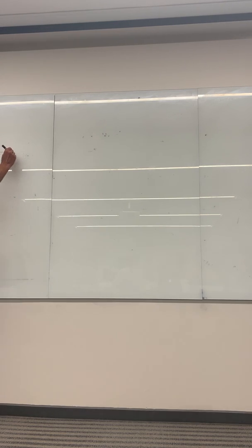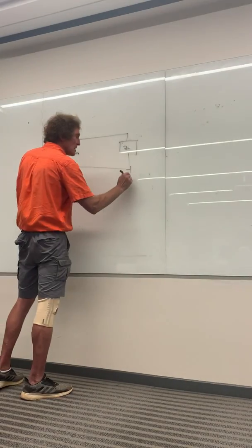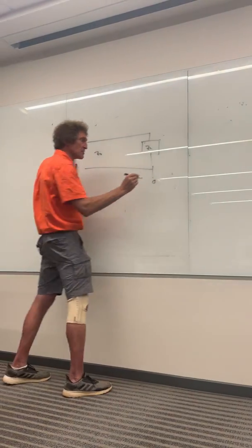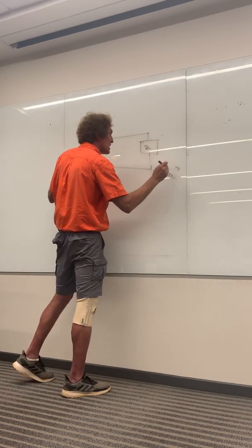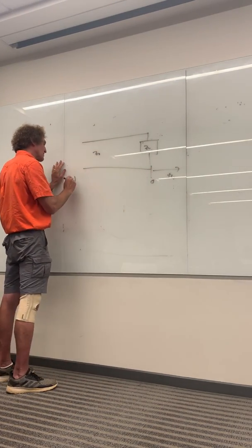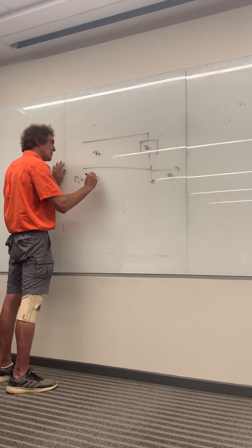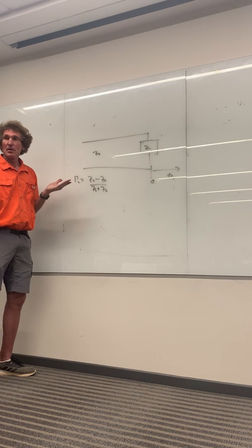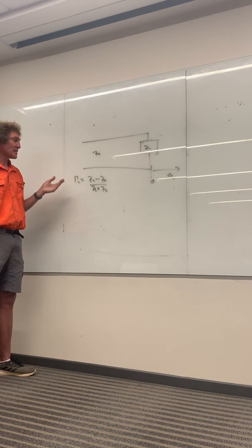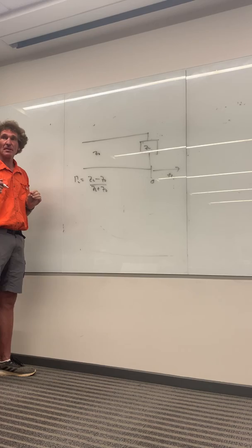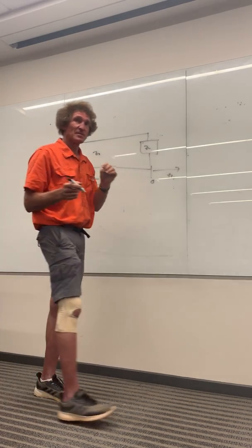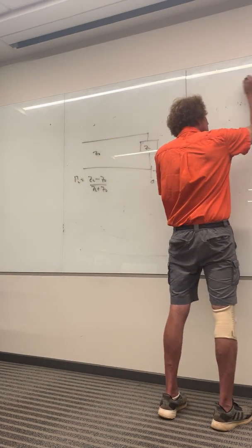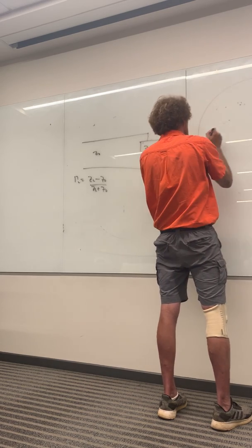Usually when we have, just write this down, or you can listen, you don't have to actually draw this. When we have ZL and Z0, I put it at 0 here, and this is positive Z. We know for a fact that the reflection coefficient on this is going to be (ZL minus Z0) over (ZL plus Z0). We know that. Well, that's bad. If we have anything but ZL equaling Z0, it's bad, right? So how do we get rid of this problem? Well, here's my little drawing of the Smith chart.